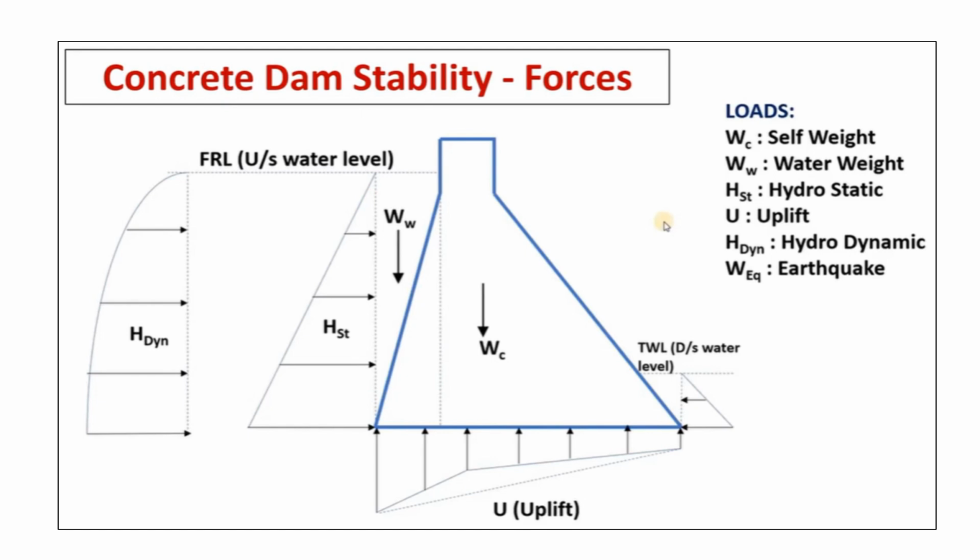The important safety check in stability is consideration of earthquake forces. Earthquake forces of dam body shall be worked out. Also, reservoir imparts extra load onto the dam. This is known as hydrodynamic load. In this video, we will see computation of these loads one by one.